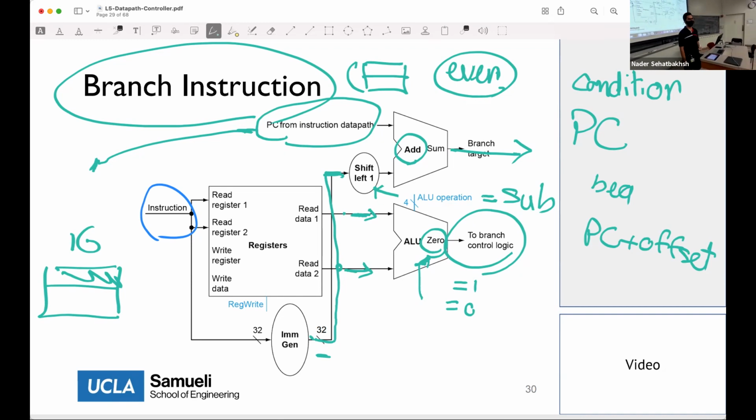No, no, it's not. It's adding this ability to be able to read 16 bits if you want to. But the way that the compiler and your code are gonna generate this code is that basically the first 2 bits will always be 0, 0. So even if you shift 1 bit, it's gonna be the same. So it's not something to be worried about. It's just a design choice that they made in order to make sure that you're only allowed to jump to specific instructions. The whole thing you need to know is that all this part does is PC plus the offset, but the offset itself is shifted to the left by 1 bit.